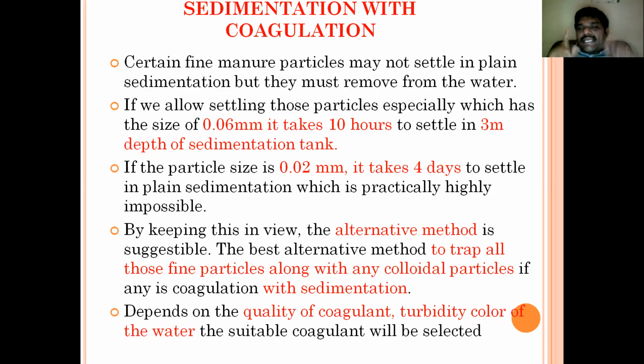If the particle size is 0.02 mm, it takes 4 days to settle in plain sedimentation, which is practically impossible, because water is coming from the intakes regularly. The received water has to be treated and sent to the public. If we store water for 10 hours or 4 days, the demand of the public may not be met.